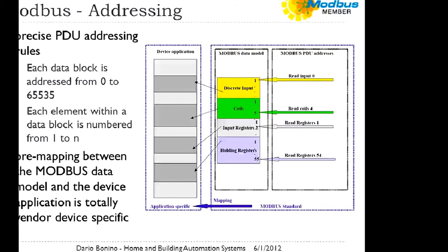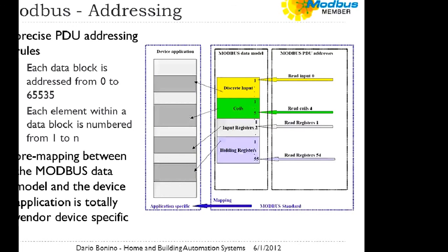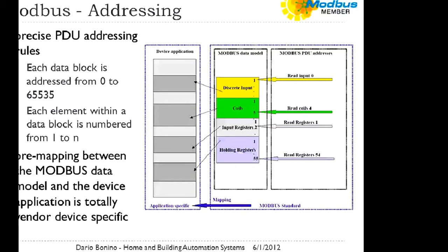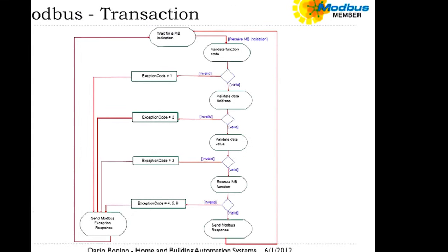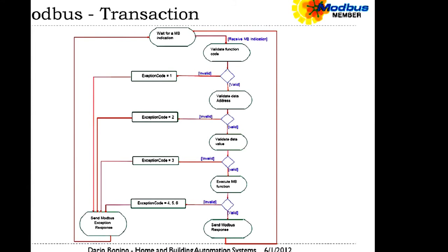So basically, if we want to read and write data on a Modbus system, we need to read and write registers to make it short, and we need some kind of mapping between the functions and the registers. And that's why every Modbus device has a leaflet saying at the address 1001 you get this data, at the address 1002 you get this data, and it takes 2 words. So you need to read also the register 1002 and so on. Okay, and this is how the communication works.